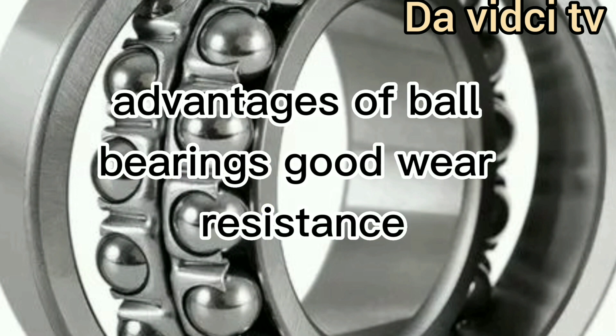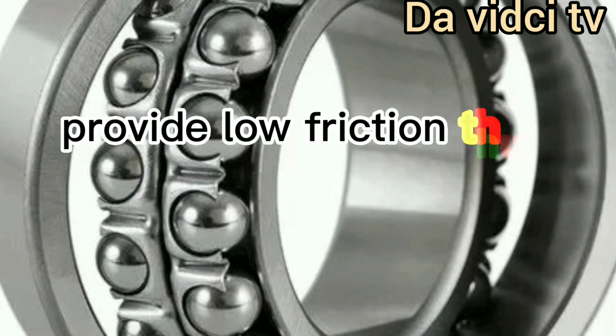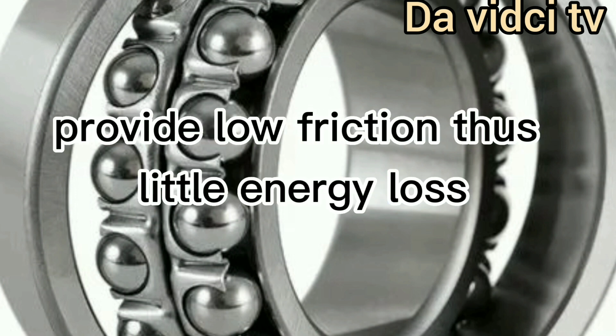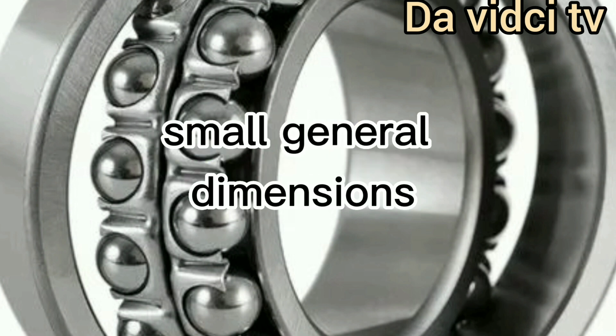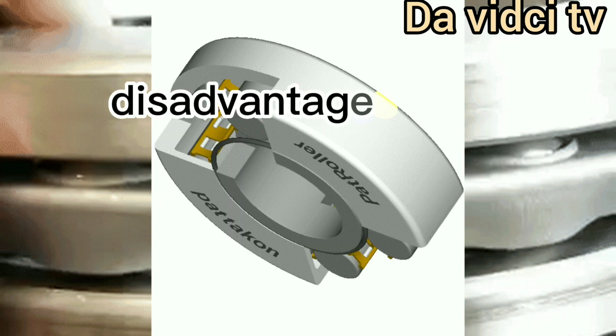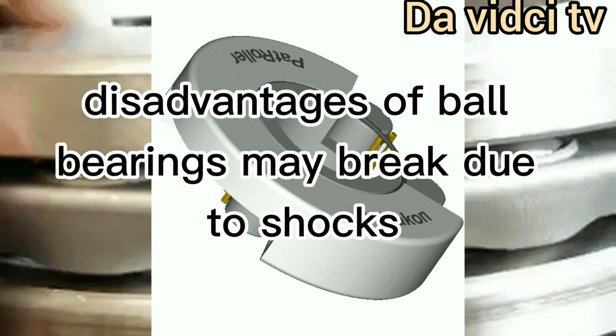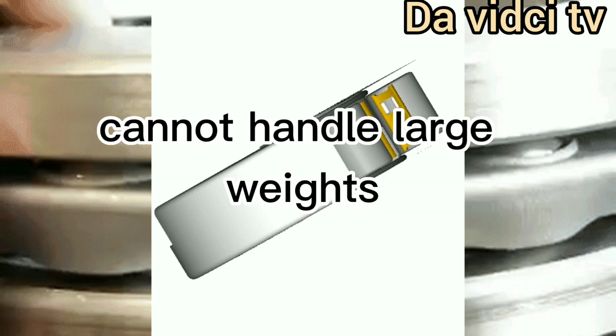Advantages of ball bearings: good wear resistance, do not need much lubrication, provide low friction and thus little energy loss, long service life, easy to replace, small general dimensions, comparatively cheap, can handle thrust loads. Disadvantages of ball bearings: may break due to shocks, can be quite loud, cannot handle large weights.